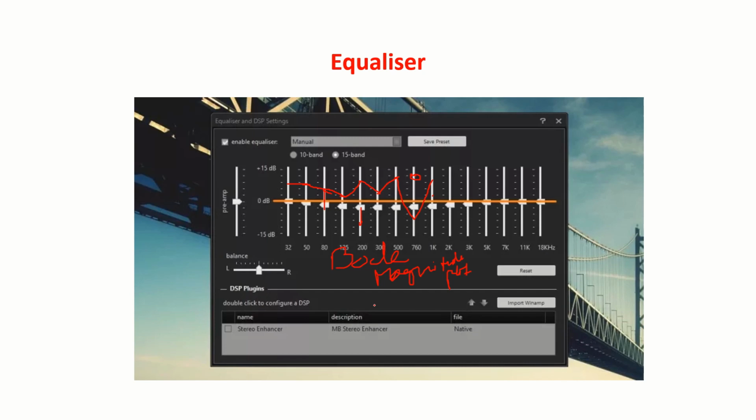Let us understand how to draw such Bode plots and how exactly the poles and zeros of the open loop influence this. Right? Suppose you are pushing it up, this button, probably the zero is playing an important role. If you are pushing it down, the pole is playing an important role.